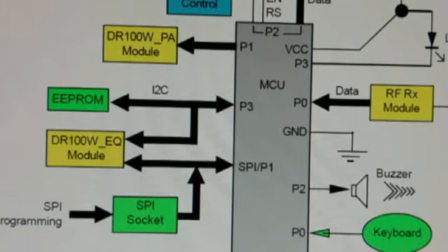That is why I have included it in the block diagram, because in managing the whole system, there is a need to take care of the digital ground, which by experience causes interference to the analog portion of the circuit.